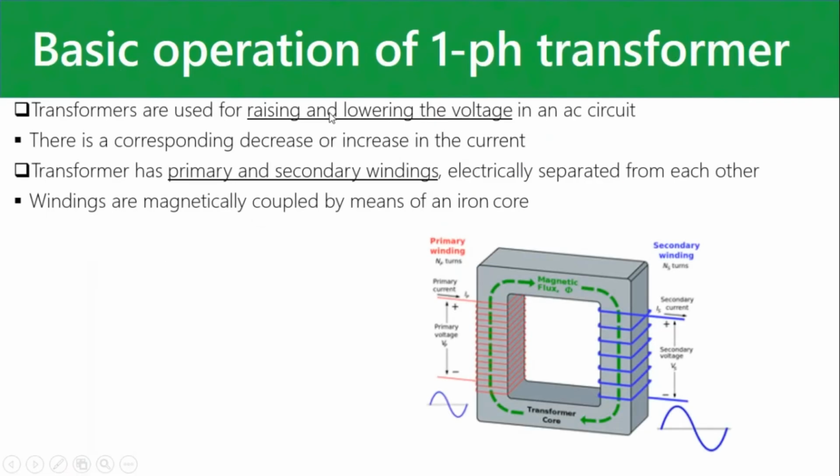All right, so transformers, basically the main use of it is to change the voltage in, let's say, a power distribution system. So you have an input, a primary side of the transformer, where you'll have an AC voltage. So there's VAC, that's your input, primary, and that consists of the windings, insulated windings, so they make no electrical contact with this core over here, the magnetic core.